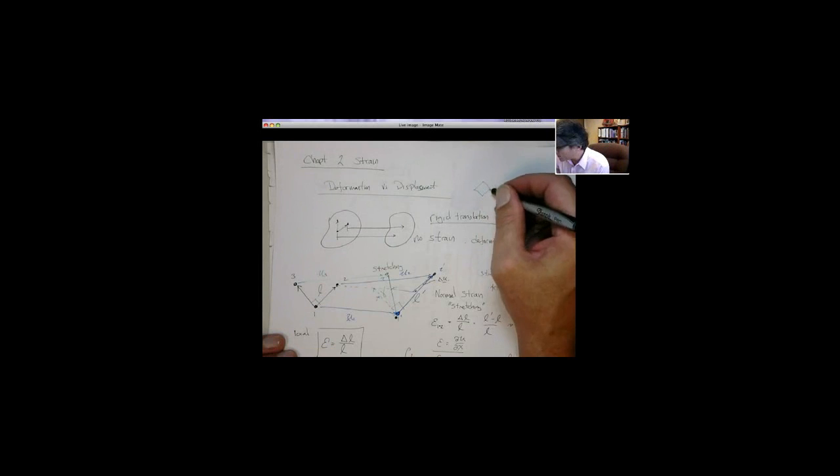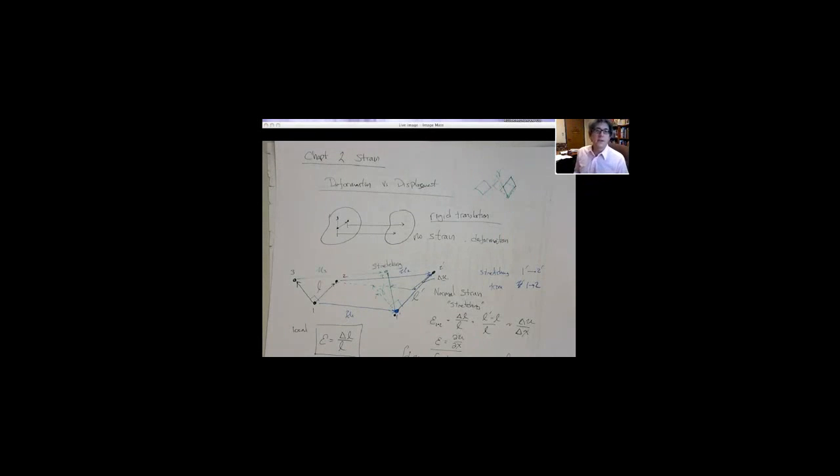So in the undeformed configuration, a little chunk of material that looks like this has now deformed to the following, where this angle here is gamma. Now, that type of deformation doesn't have any stretching associated with it, but there's still definitely deformation. And the deformation you can see is associated to that angle change. So it really only makes sense when you talk about it relative to another line, but that gives you this angle change gamma, and that is the shear strain. So gamma is the shear strain, and it is that angle change.